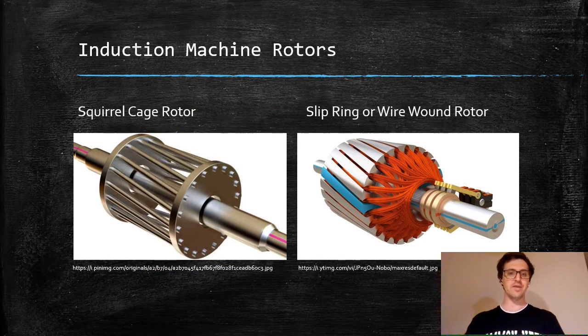Induction motors are inherently self-starting and do not require a permanent magnet, brushes, commutator rings, or position sensors. Squirrel cage rotors have two end rings that are interconnected by several bar conductors. In this arrangement, the rotor is a standalone winding and cannot be physically accessed to change the rotor current or phase to control the motor torque and speed. Slip ring rotors are similar in construction, but instead of bars, windings are used as conductors in the rotor. The windings are then connected to an external variable resistor so that the electrical characteristics of the rotor can be altered to control speed and torque.